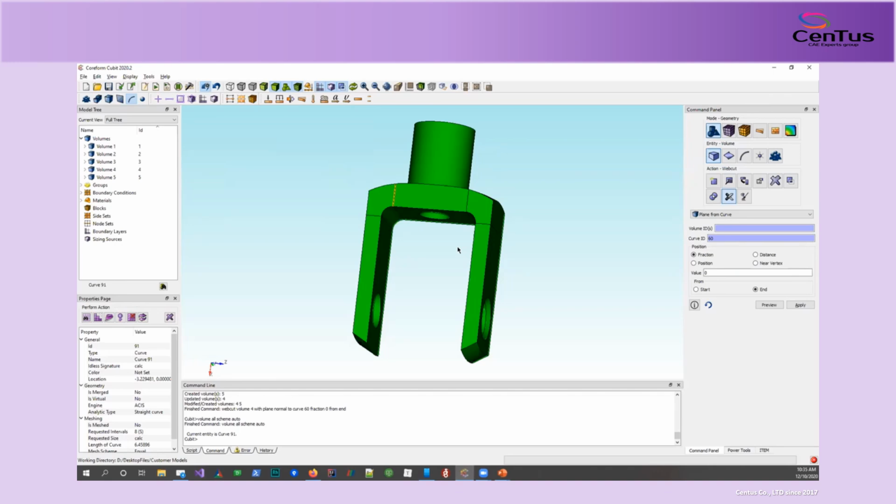When we do the imprint and merge, we take the curves, map them from surface to surface, and then we merge those surfaces so they're shared between the two volumes. That's what merging is, sharing those surfaces. And this is the step that is a little bit unusual for new Cubit users. Other tools might do this. They have to do the same thing, right? Effectively, however they do that. In this particular case, we make it an explicit step.